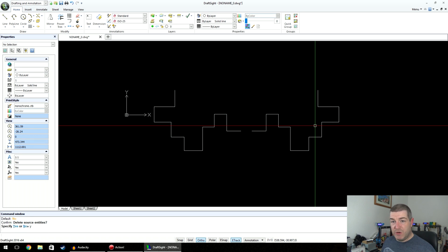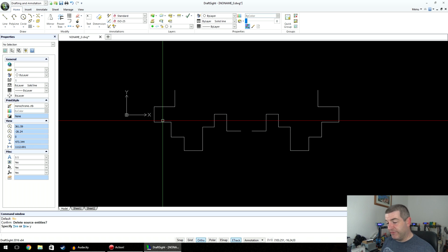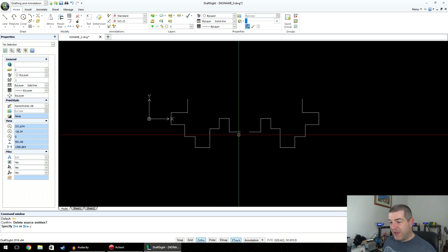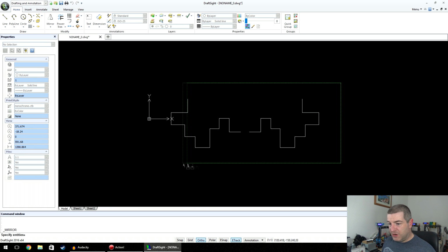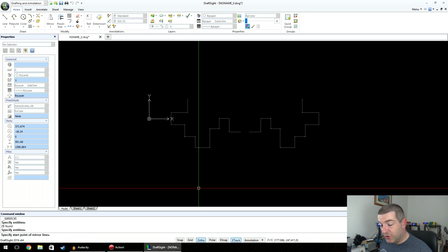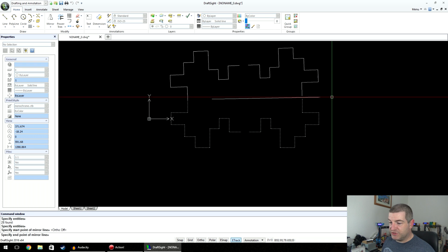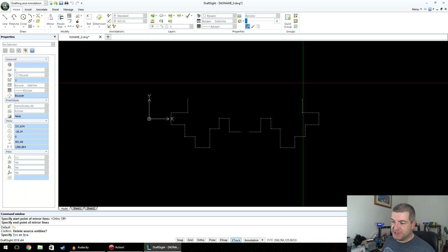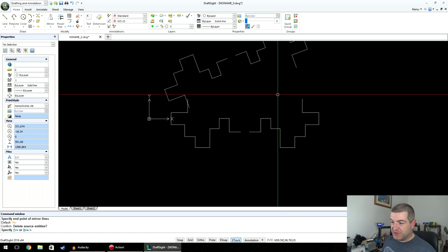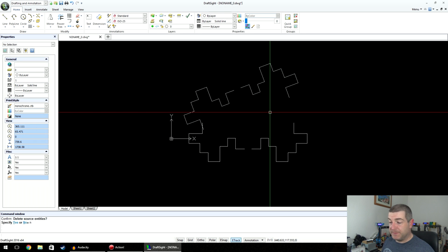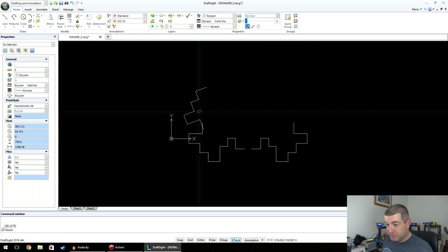copy. So mirror is a really handy way of duplicating something that you've already done, but flipping it over at the same time. There are other ways you can do things like that, but it's a bit weird. You can mirror on any angle as well. So if I turn ortho off, and we just choose, instead of going straight up or straight across, if we go at an angle, as you can see, we get some kind of bizarre effect if you really needed to do that kind of thing. But that's mirror. That's what mirror does.